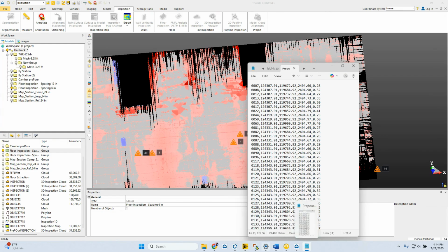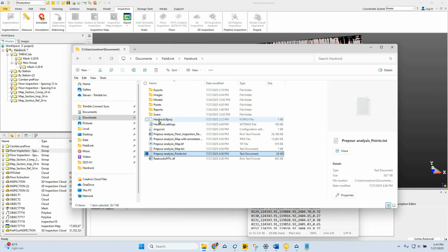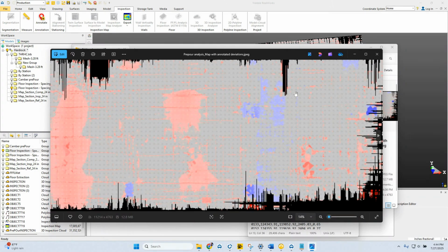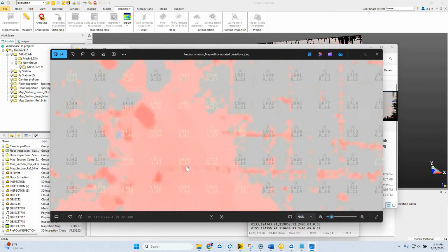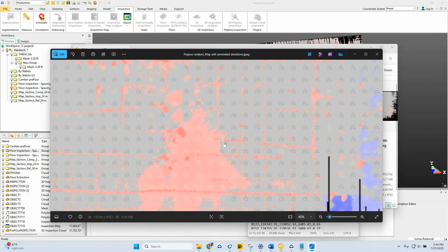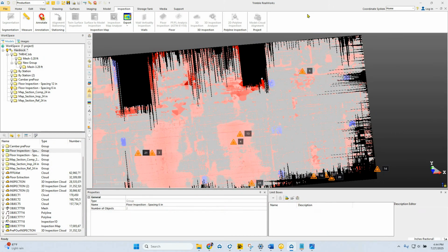The other thing that will also be in there, just to give you a better idea of where those points come from, is here's that same pre-pour floor. We can see some high spots, low spots, and in red would be above the 1/4 inch deviation that we had for analysis in between those two. So you can start to see where that's high. So I can create that.